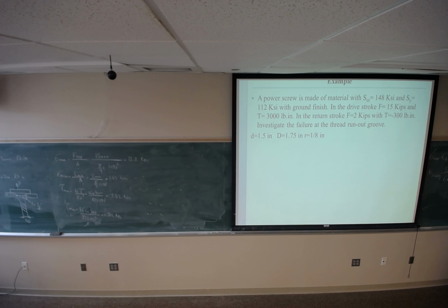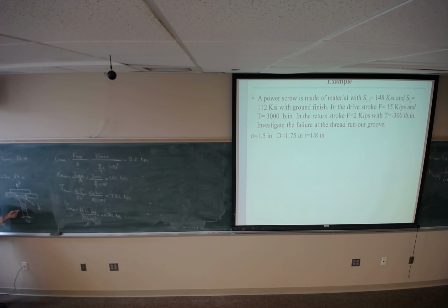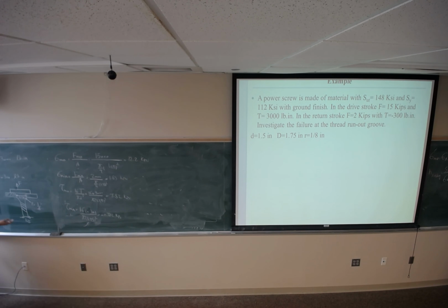He's saying the slide is right, because you've got a larger diameter at the top of 1 3/4 inches. If you've got the radius on that fillet of 1/8 inch, you're taking off a 1/4 inch total in diameter, so the minor diameter would be 1.5. No, these two are not related to each other. The fillet can be anything. It's the radius of the curvature of this side, not the thickness. The fillet can be sharp or not, so I can put it 1.3. Okay, make sense?